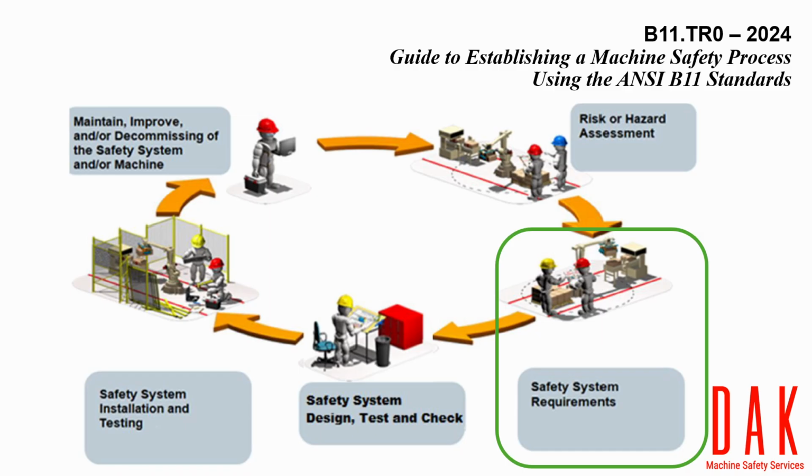When a machine is part of a larger overall integrated manufacturing machinery system, requirements concerning safety layout, span of control, and safety-related functions, interlocking requirements can be found in B11.20, Integration of machinery into a system. If the machine or system can be accessed remotely, requirements concerning cybersecurity can be found in B11.TR0, Consideration of cybersecurity aspects. Acceptable risk and/or appropriate risk mitigation techniques may depend on the industry, equipment type, and the environment in which the machine is installed.